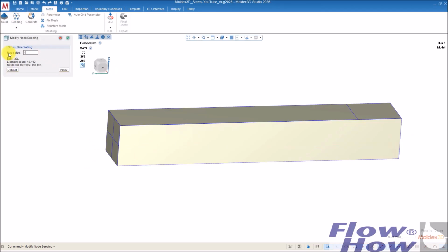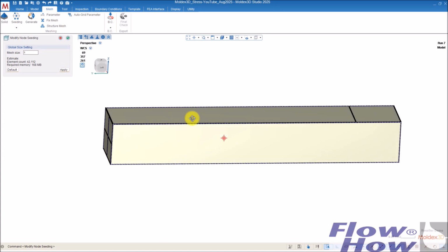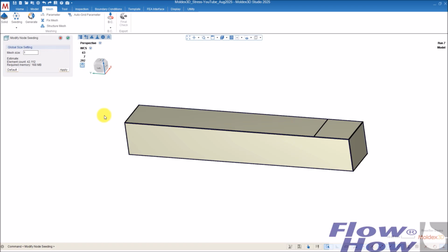And then I'll put a mesh on it. I'll make it quite fine, because if I have to rely on the stresses, then it has to be a fine mesh. Not all over the part, but in this case, the simulations are so fast, so it's not a problem if you run a normal linear simulation. When I say normal linear, Moldex Stress covers primarily small deformation and only linear material data and no contact analysis.